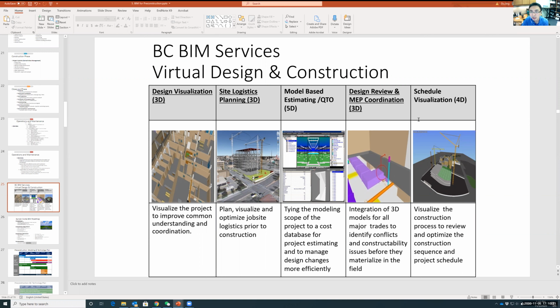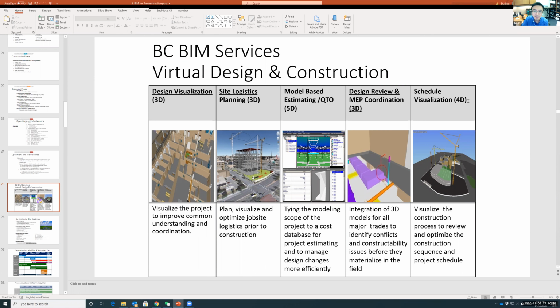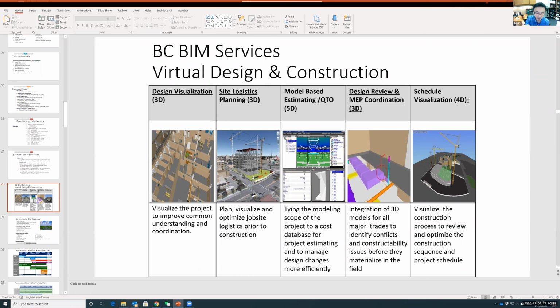And of course, pre-con also involves schedule visualization, the 4D simulation, because this is a good way for you to see how it's built up. And because you visualize that, there's a bigger chance you discover potential issues during the operation, not the clash detection. That's why somebody calls 4D simulation the temporal clash detection. Why? Clash detection considers the finish of the project. So let's say the job is done, now I want to run and see the spatial conflicts. But the 4D simulation can also tell you the time conflicts.